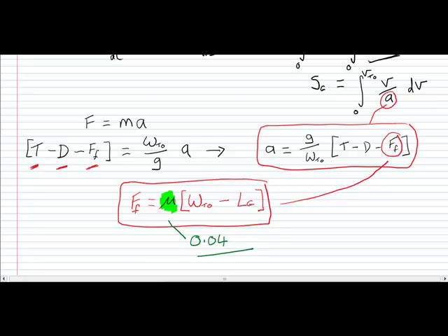So once you've got all of those values, you're in a position to work out the thing that you're interested in, which is going to be the primary component of your takeoff distance, your S_G here. It's an integral that you have to compute, and the best way to do this, given the data that you've got as inputs to this integral, is to integrate this numerically, and we've given you a code to allow you to do that.